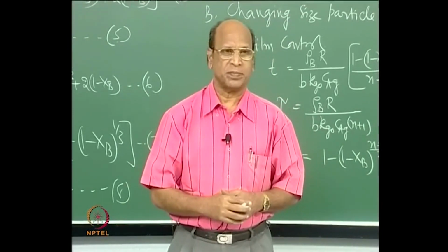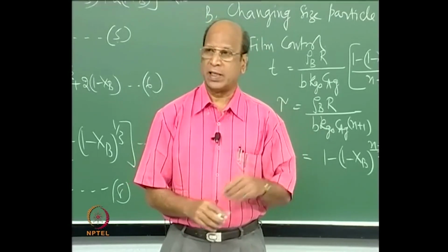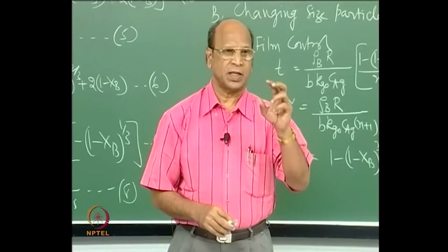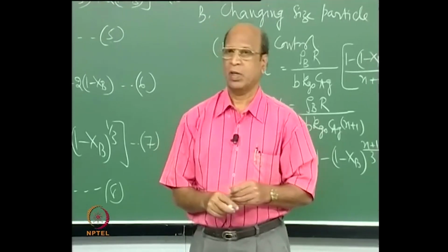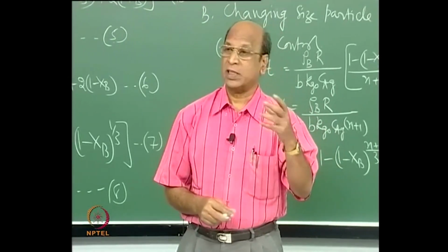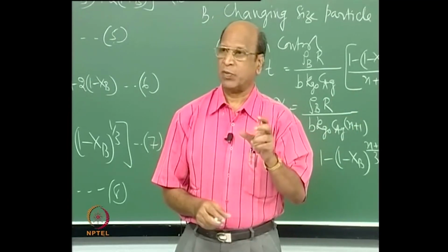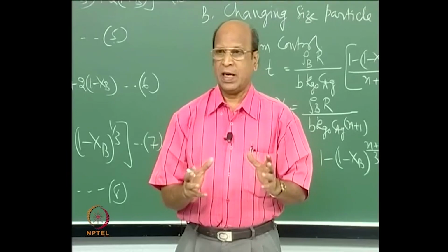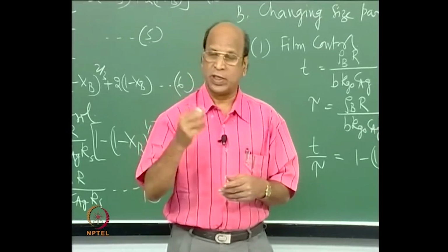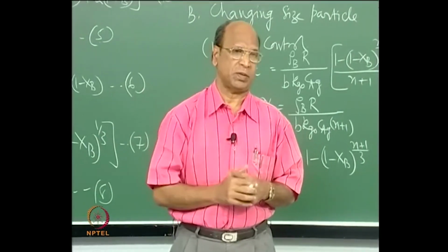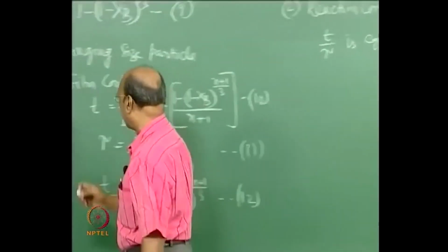Once we do that, we should also take one more thing into account. This I have mentioned in the beginning, as usual I think you may not remember. I told you that our most important phase is the solids in non-catalytic reactions in many cases, okay. Almost 99% of the time we are more worried about the conversion in the solids rather than the conversion in the gas phase. So, that is the reason why solids are our important phase, and once you have solids as the important phase, then we have to treat the solids as what is called macrofluid. Okay, I will write here: macrofluid.